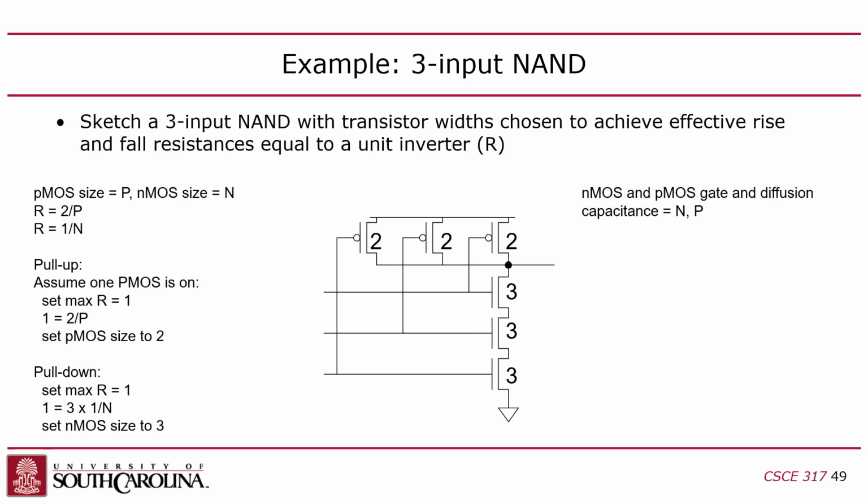And so we want to reduce the resistance. We want these NMOSs to have lower resistance because they're in series, right? And when you have them in series, you're adding resistance. These guys are in parallel, so we can afford to keep them small and have relatively high resistance, right? Does it make sense? So that's how I've got these things sized. Okay, so what do we do about that?